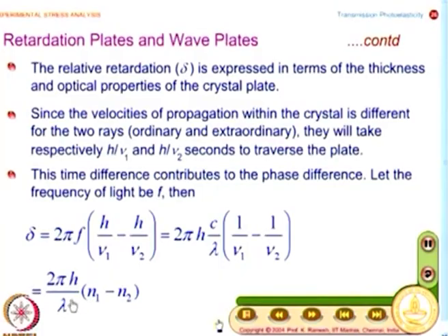It is very important. See, I said that for the mathematical development of photoelastic analysis, the mathematics becomes a lot simpler if I confine our attention to a monochromatic light source. Where does this come from? Till now we wanted to see colors, so we used white light, and we enjoyed seeing those bright colors. But when I come to mathematical analysis, we find a crystal plate behaves like a quarter wave plate for a given wavelength. The same is applicable for wave plates as well as the model behavior.